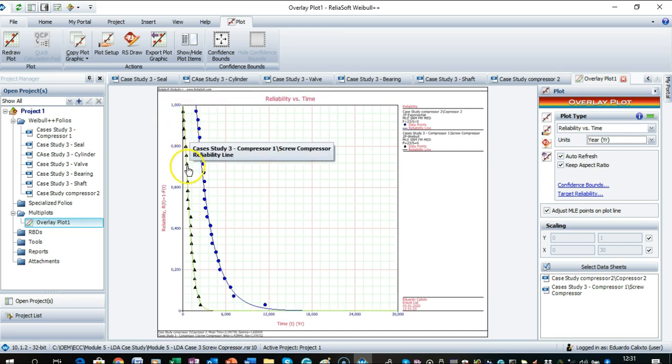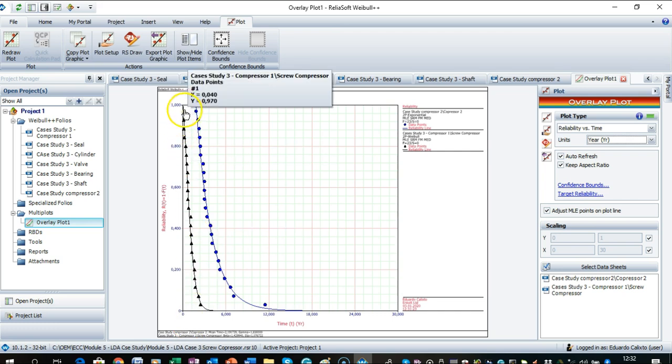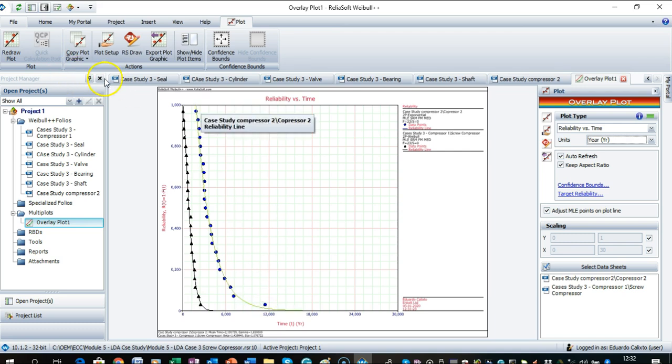So my prediction of reliability is very low. For example, if I predict the reliability for a specific period of time and have a target of 2 years, based on this approach I will tell that it is not achieved. But actually, I collected my data with the interval of data wrong. If I apply the proper approach, I will get these parameters. And then, as I explained during the training, the real better approach is to have each component's PDF and look at it to take some preventive actions.